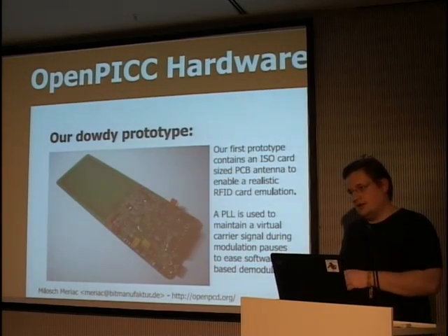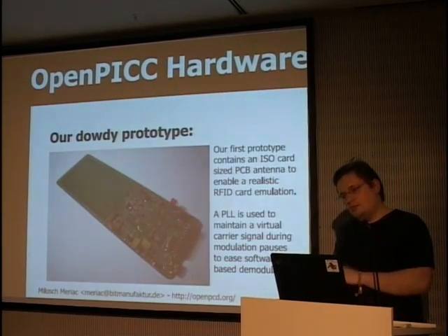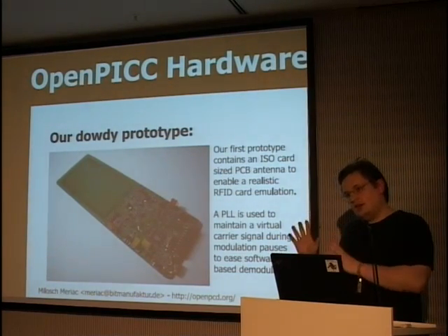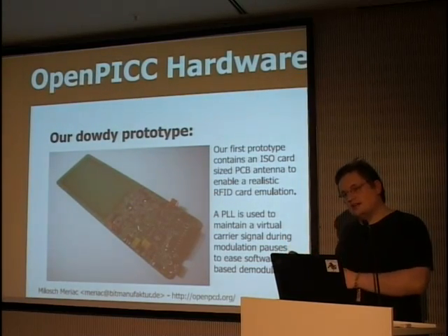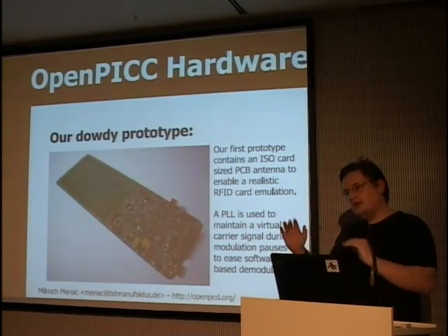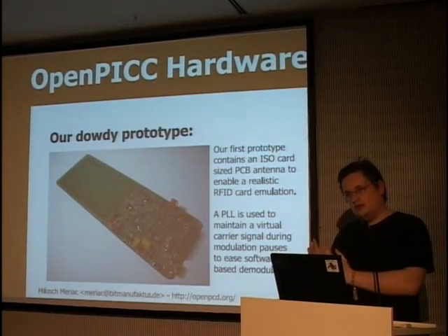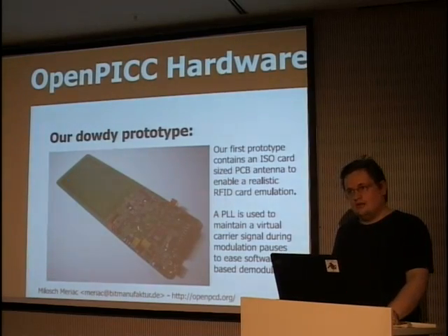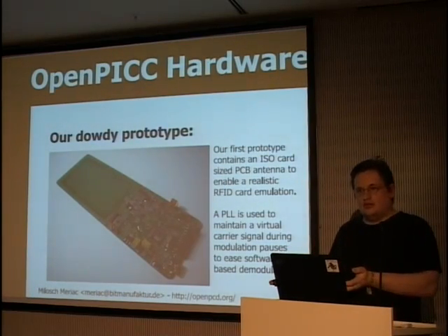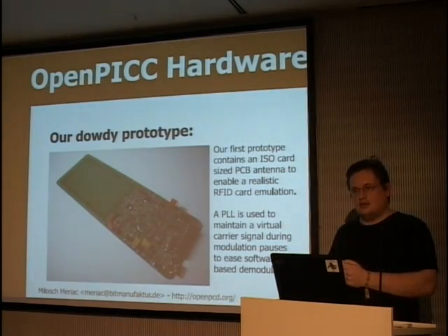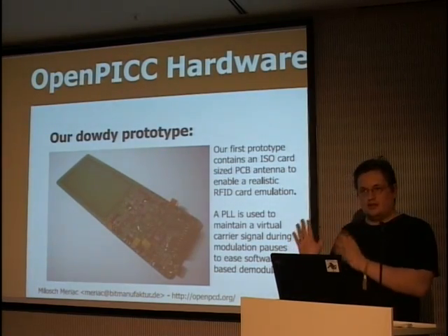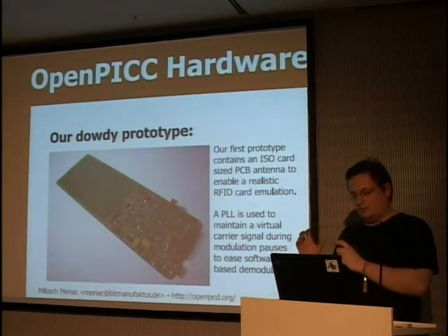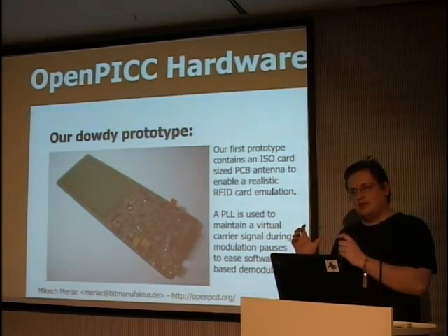It's used all around the place for our timers, for our counters, and whatever. But the problem is, if you have certain cards, the modulation is 100%. This means automatically that the signal is away, and after a given time, it's there again. But during this time, you naturally don't get any cycles. So it's like the world had stopped for the OpenPICC card.